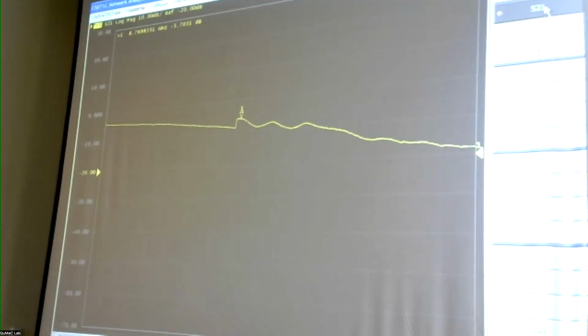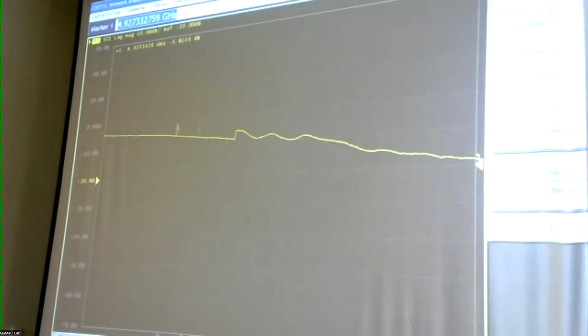Fairly low attenuation. In fact, this attenuation is also a little on the higher side, but okay, minus 3 dB. My suspicion is that the instrument currently is not optimally calibrated, and I'll actually talk about that a little bit later. And then it slowly increases, the attenuation increases. And that's just because this is a finite conductivity cable. And at higher frequencies, you're going to get more loss, both due to the dielectric and the metallic response.